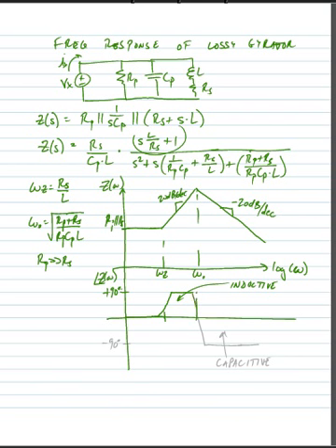Just before the resonant frequency, the phase shift would change to minus 90 degrees, and it would stay there throughout all higher frequencies, and we would say that this would look capacitive. In other words, the impedance is decreasing with the increase in frequency, so it looks capacitive.